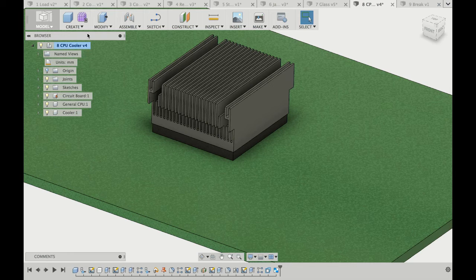How do you figure out which U values to use when the FEA is taking the geometry into account? What I did for this demo, I just searched the internet, specified the type of the problem, and found the empirical value that people are typically using in these scenarios. So it looks like these factors are relative to the situation you are in. So the easiest way is to find out, like, Google it. If you are not into it, as I'm not, I guess if you are an expert in thermal, you will have your own tables, or your company will have some standard procedures for what factors you should use. But if you don't, the Google will give you good suggestions.